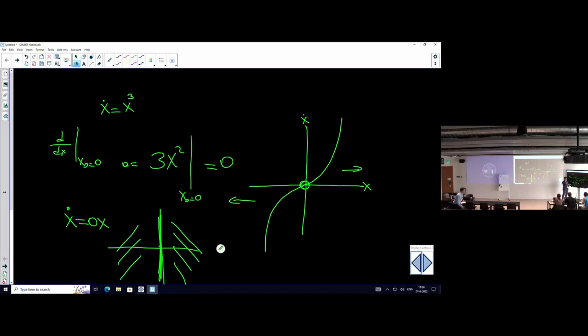Yeah, because if I have a higher order system, like a fourth order system, I'm trying to write the states in a way that I will always have the velocities on the left-hand side. So if I have 4 states, I'm just writing x1 dot is equal to x2, x2 dot is equal to x3, x3 dot is equal to something, and then x4 dot is equal to something. So on the left-hand side, I always have the velocity. This is the representation of state space.